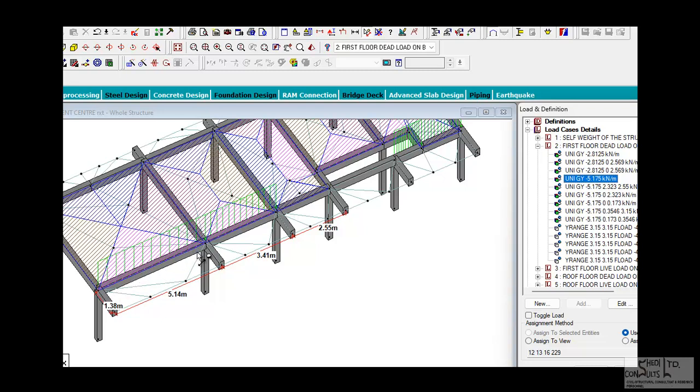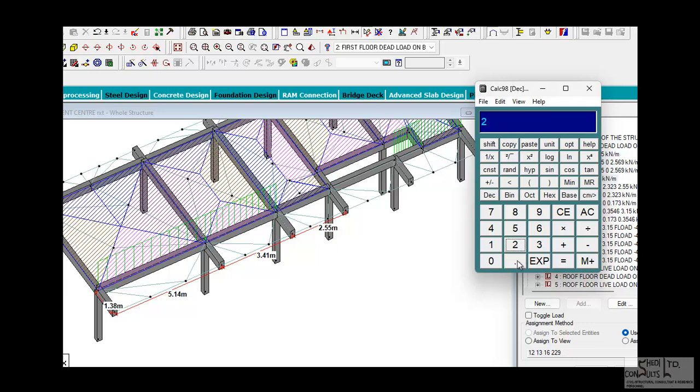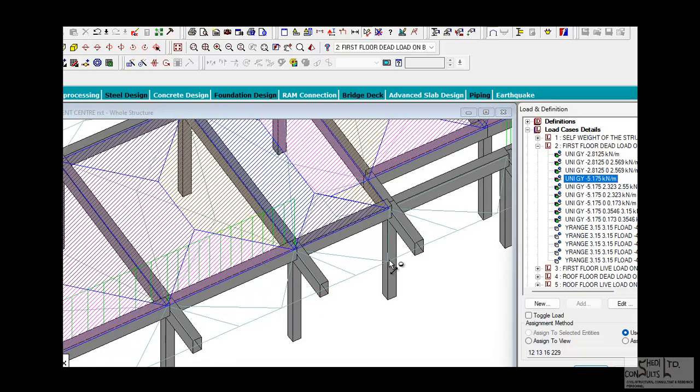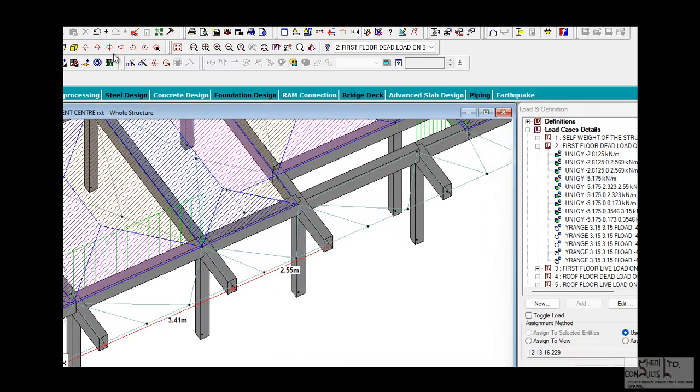is in order here, but it is wrong in this slab panel because this slab panel is not a one-way slab. Why is that so? Now, for that slab panel, the ratio of the longer to the shorter side is 1.84. So this slab panel is a two-way slab.